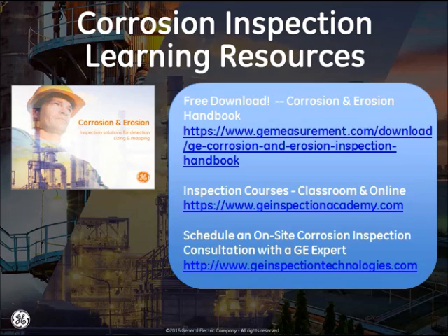So typically what happens there is there are products available on the market using magnetic flux leakage. It's kind of like you're pushing a lawnmower around the inside, but in the process, you're using flux leakage to determine the suspect area. Once you locate it, then you can go in and do corrosion mapping. And then you can fine-tune it even more with a point ultrasonic measurement. So, yes, the short answer is typically the design engineers know where their concerns are, either based upon design criteria or upon experience, and then based upon that, you can go in with a mapping solution or even a point measurement solution.